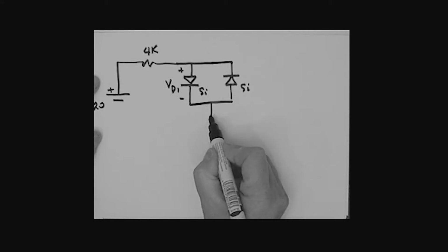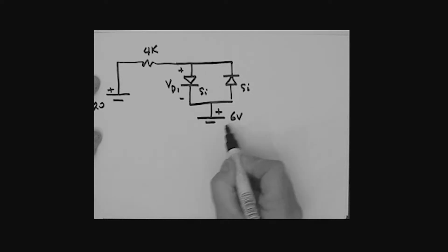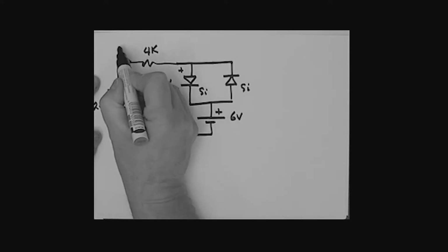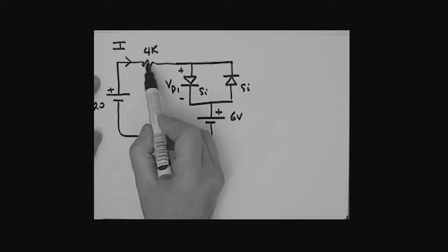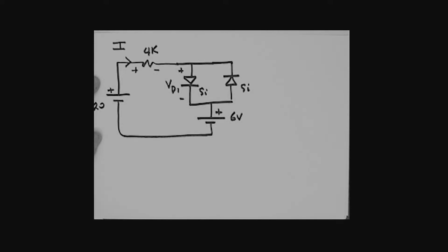And then we'll put another voltage source right here, plus, we'll say that's a 6 volt source, and that is the circuit that we are now trying to deal with. What we are trying to find in that circuit is the current I. Once again this will break down to a very simple problem. It will be just taking a loop. If this is our defined current direction here, then the voltage across that resistor is plus minus.